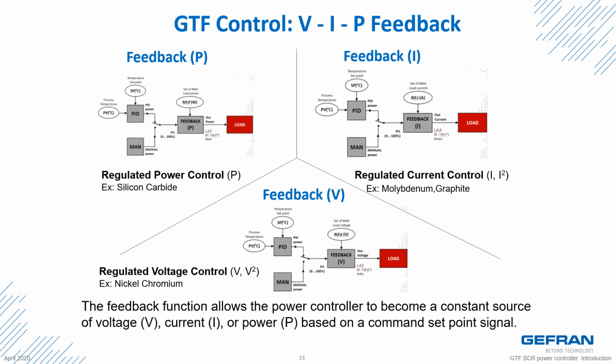The GTF power controller can provide voltage, current, and power feedback. This capability allows the GTF to be set up to control the heating elements to the manufacturer's recommendation or requirement. Power feedback provides regulated output by power. For example, silicon carbide elements might use power control.